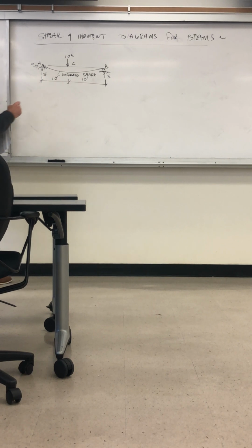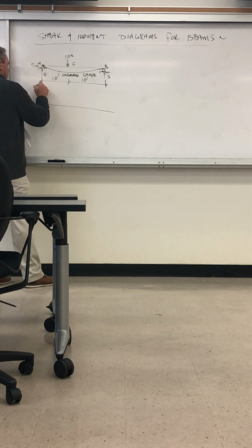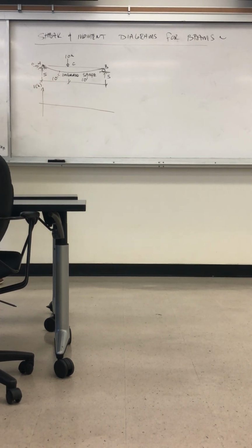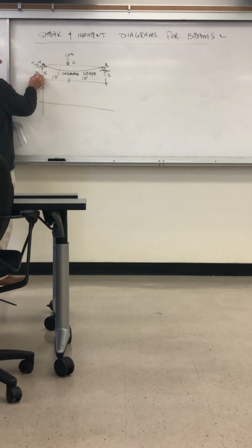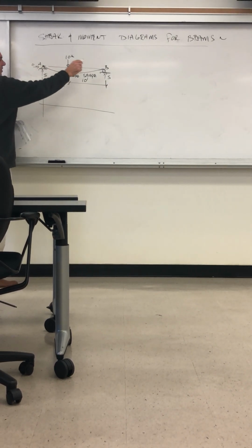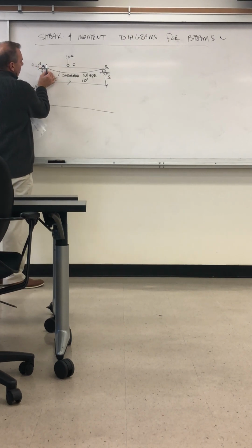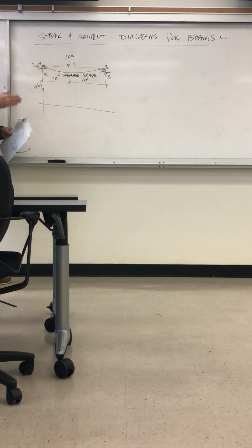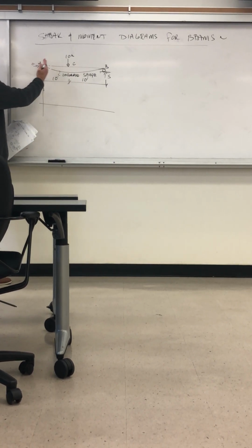Let's look at the shear diagram. So the shear moment diagram, let's talk about that. This is in kips. Every cross section of this beam, as you enter into the structure with this load applied, every cross section. So this beam is a single line drawn along the centroid of whatever the cross section looks like. But it feels the whole cross section of that beam, if it's an I section, a rectangular section, whatever it is, it has to resist 5 kips, right? If I take a cut right there, there's a force up of 5 kips.